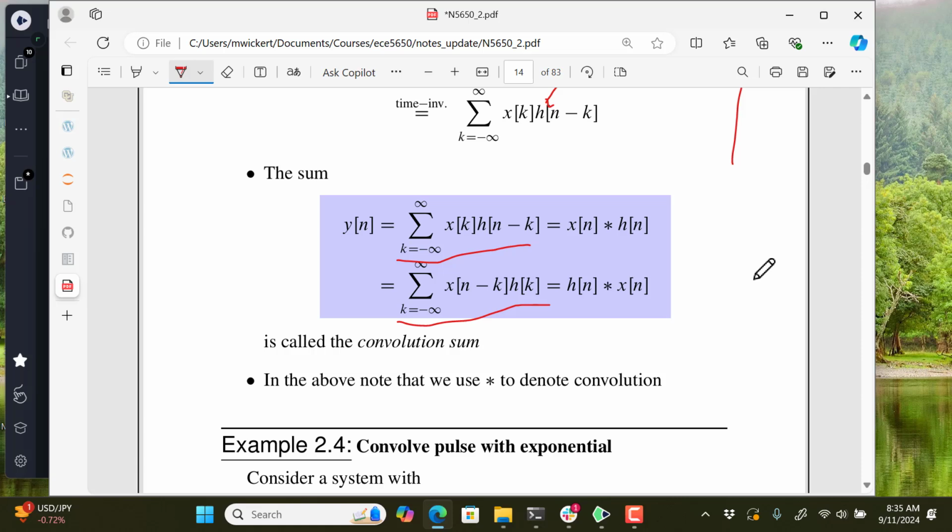So the convolution sum is more or less an analysis tool to get the output from the input and the known impulse response. In practice, though, we have the system represented in a box as a difference equation which cranks an algorithm. We can put any input in we want, we can get the output. We don't really have to have the impulse response, although that ends up being involved in an indirect fashion.